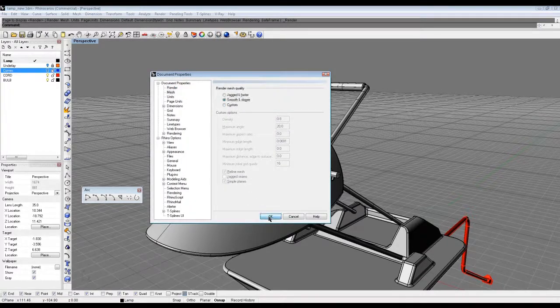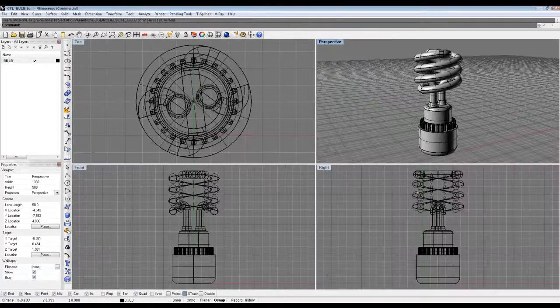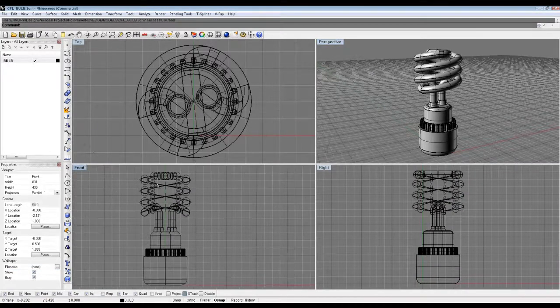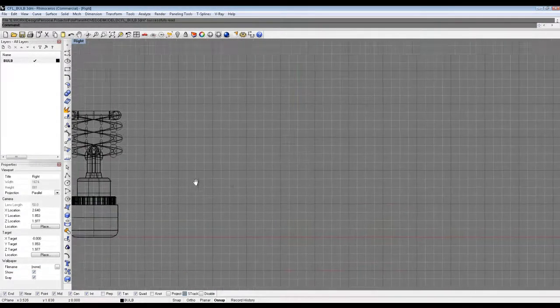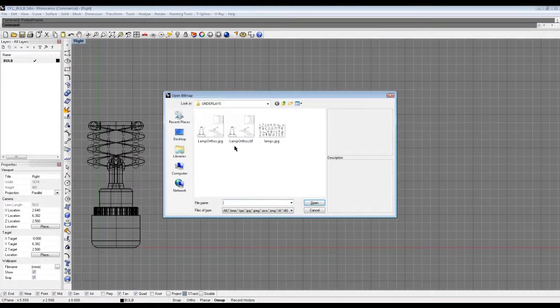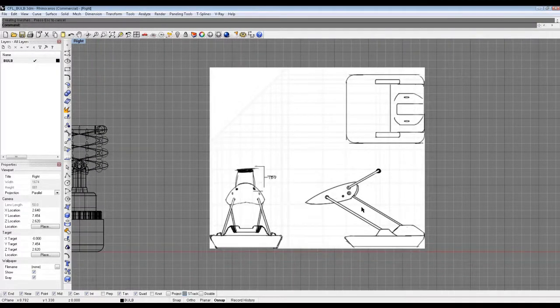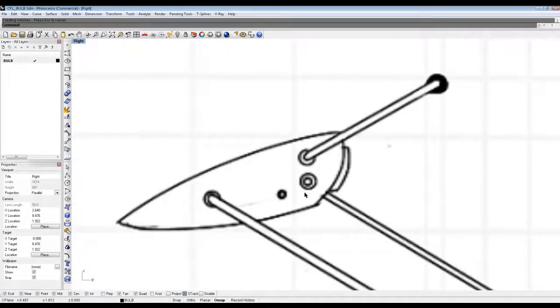Oh, yeah, sure. So Lance, you may have joined a little bit on the late side. I don't know. But I can show you real quick, we'll use the bulb as a sort of blank slate. So what you do is you can do it a couple of ways. My favorite way is to use the picture frame command. So you type picture frame, and then it'll look for a file, and then you can put a whole slew of different file types in there, and then just drag out your size. Now, one quick thing to note, you actually bring up a great question and a great point with this, is how do I know what scale this is?